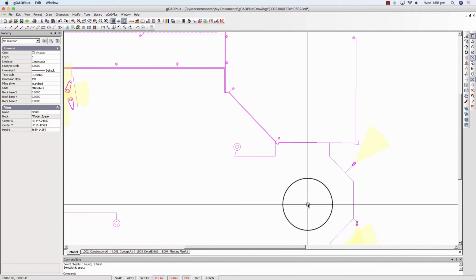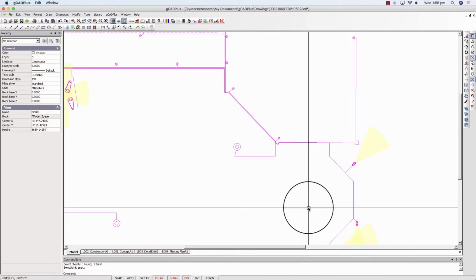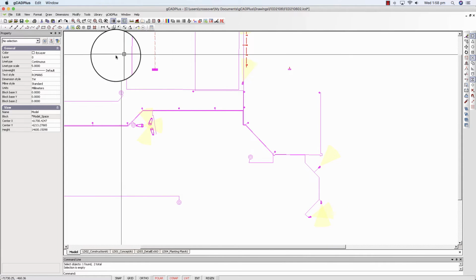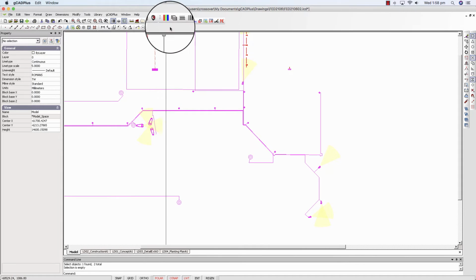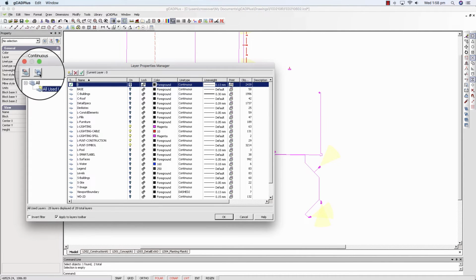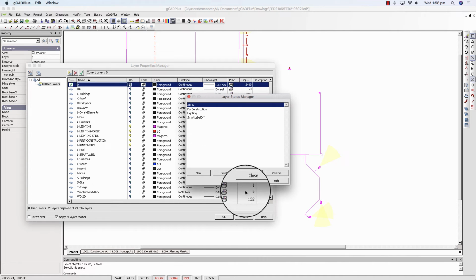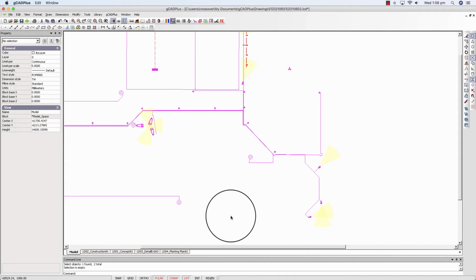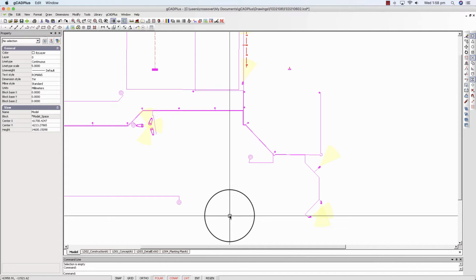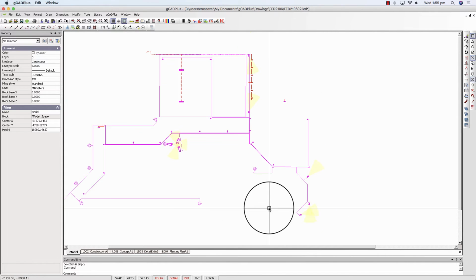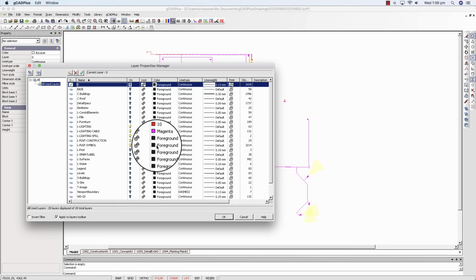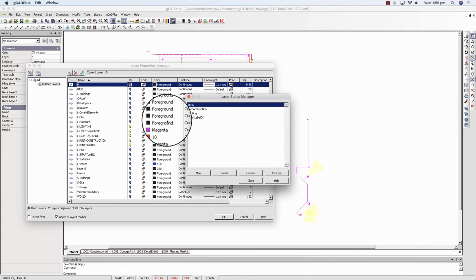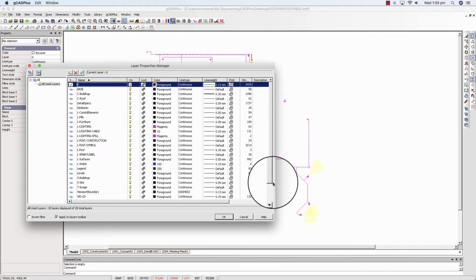They do have elements in that L plant symbol layer, and when we go back to all on, we go in here, we can say let's have everything on, and we'll close that. All layers come back on. Why didn't they come back on? Because I missed the crucial point, which is all on, but I need to restore it. And okay,